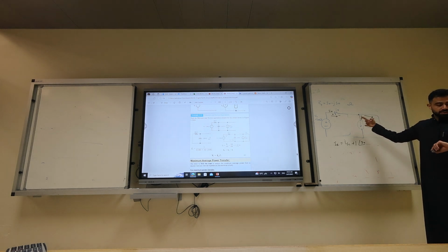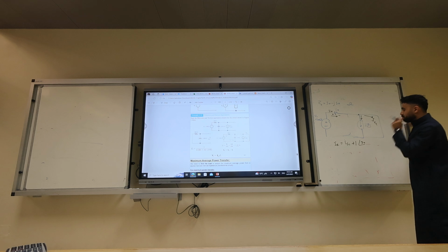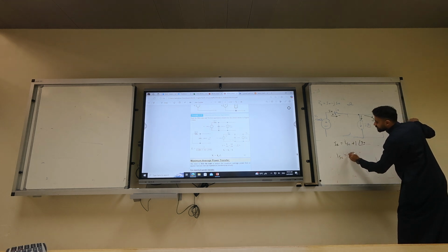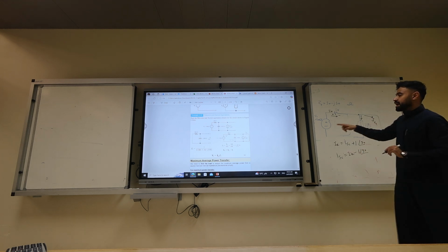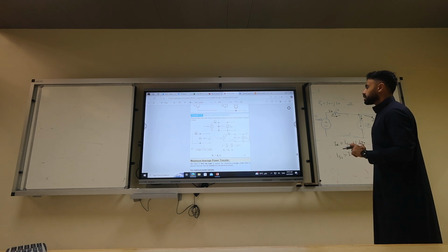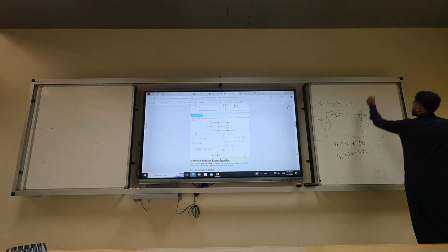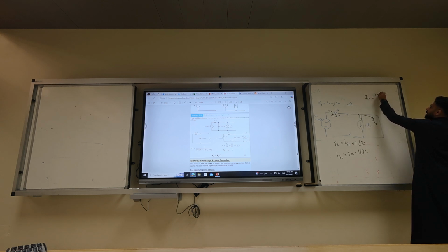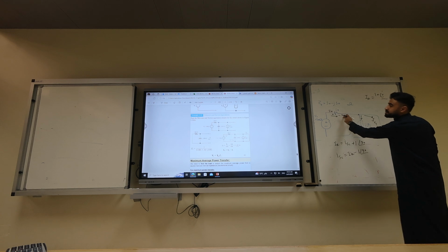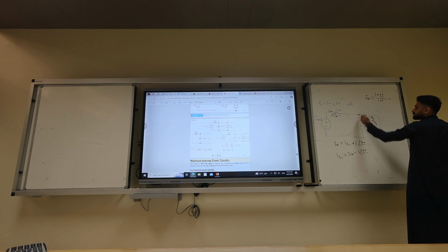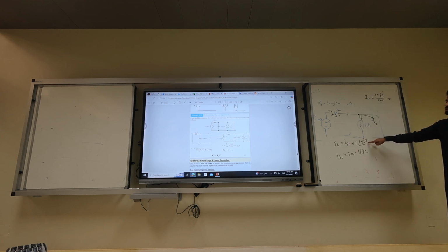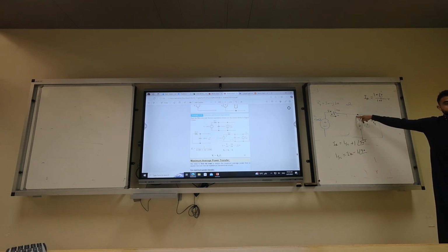If you short circuit the current source, that's okay. So, what do I want? I want to calculate I short circuit, which is IR minus 1 angle 90. What is IR? IR is 100 angle 0 divided by 100 ohm. What is the voltage here? I'm short circuiting. What's the voltage here? It is the same, 0.